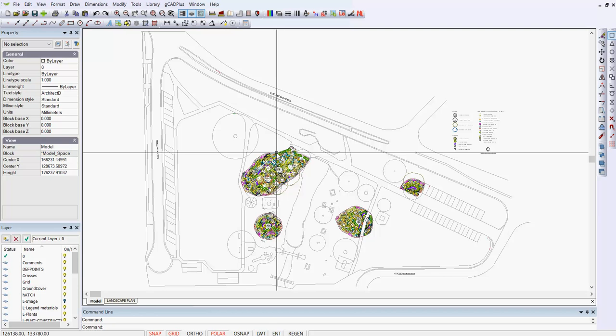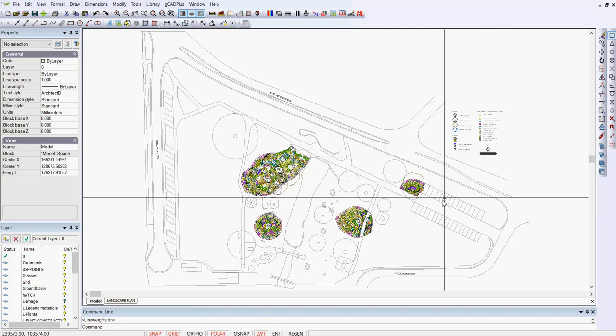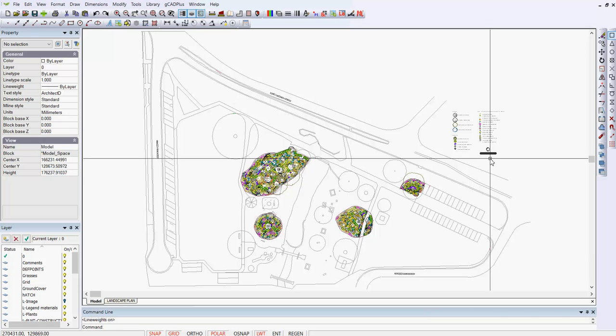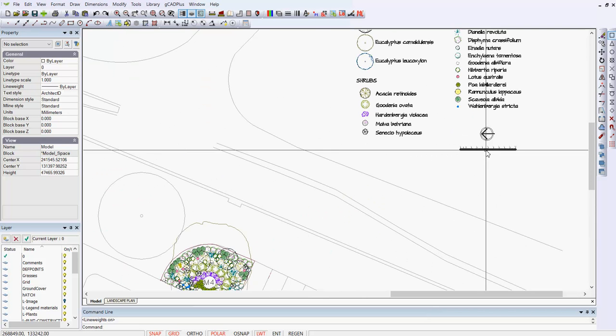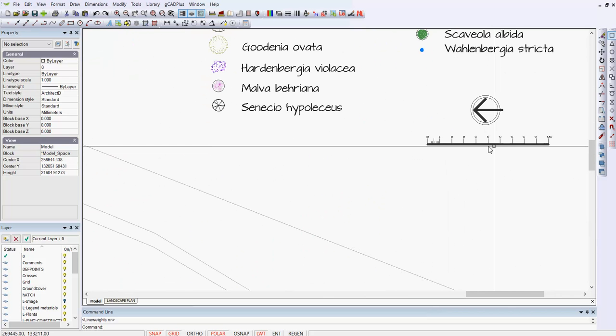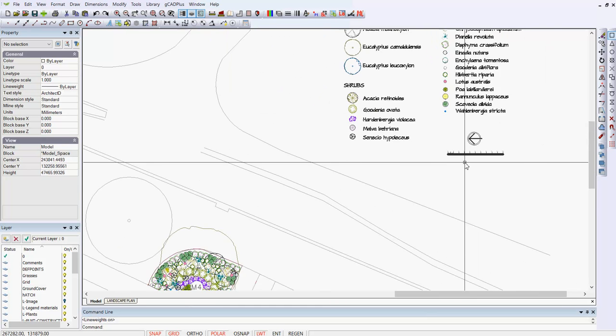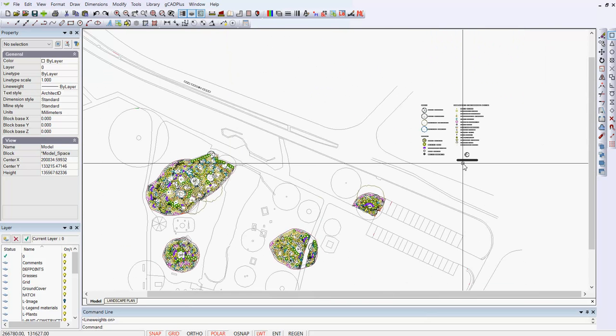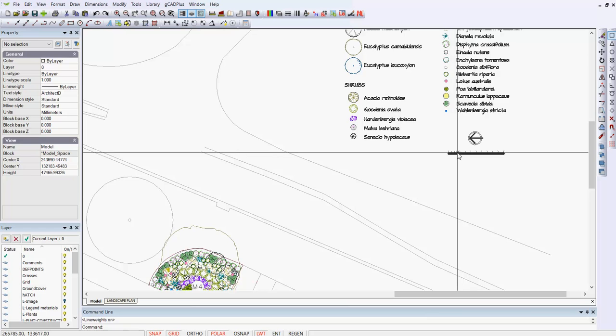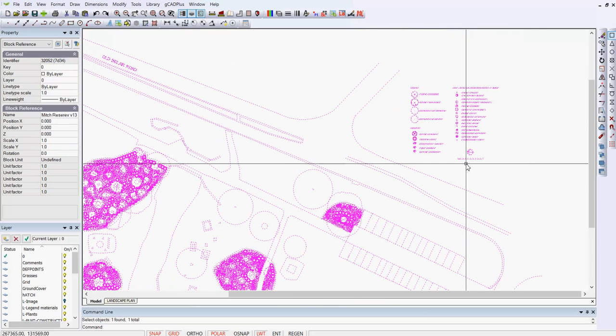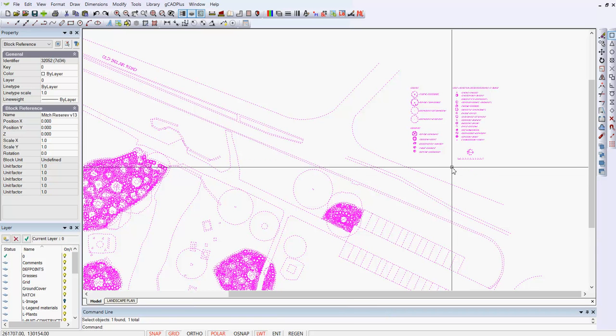If we turn on lineweight, you can see over here on the right hand side the scale has a very thick line through the base of the scale, and that's something we need to fix. So I'll click on that now, and when I do that, can you see that the whole design has been made as a block? That's really not a very effective way to do things, because if I want to edit, I've got to jump into that whole block.